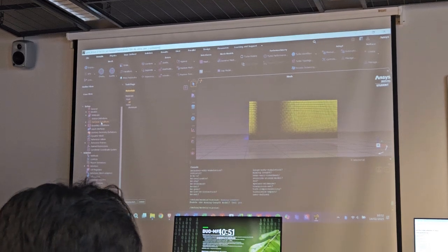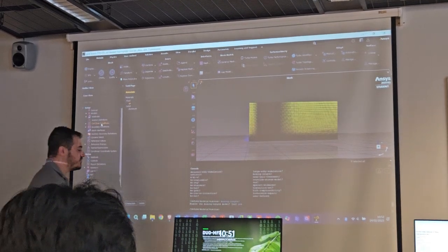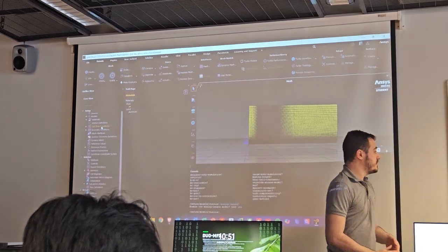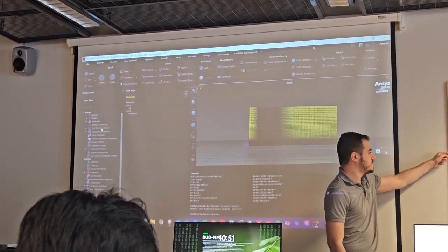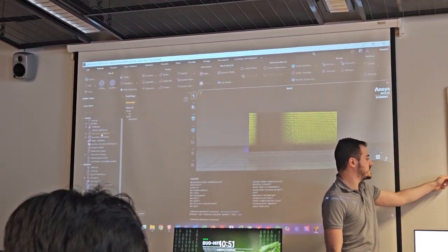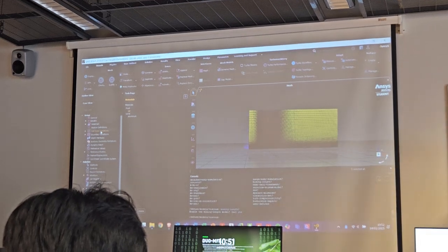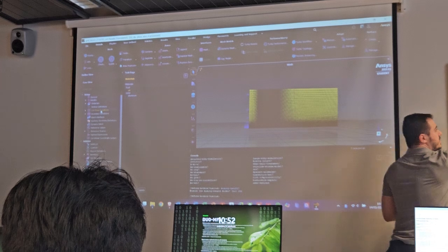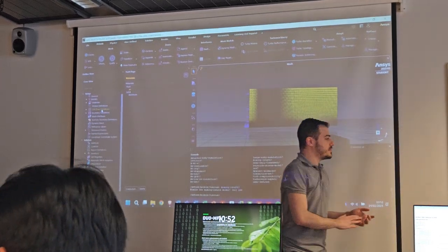Next we should set the boundary conditions. So now we have the grid, the fluid, and the turbulence model. For our domain, we need to set the boundary conditions: total pressure and total temperature at the inlet, static pressure at the outlet, slip wall for this section over here, and symmetry on the top.